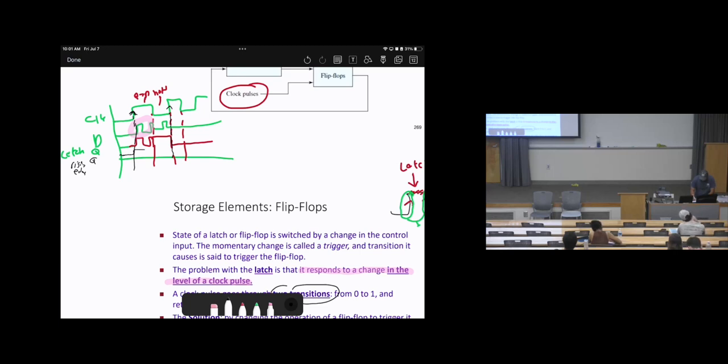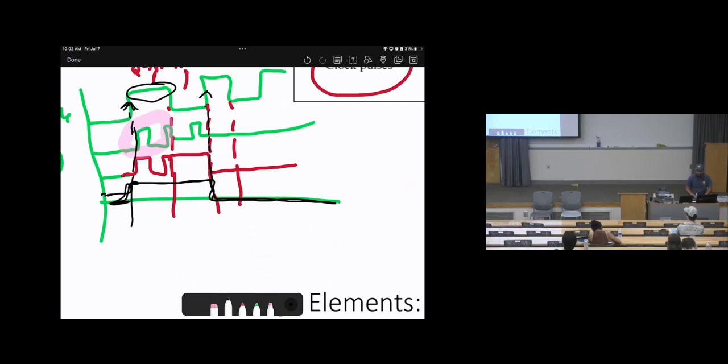Then it will keep on, hold, until the next status. This will be off, 0, then it will be 0, and so on. So we will see that the flip-flop will be updated only once, while the latch will keep monitoring what's happening. The flip-flop will only detect either the rising edge or the falling edge.